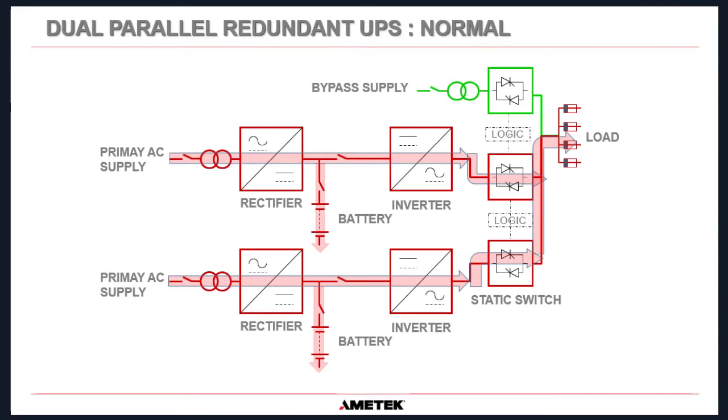Okay. So the other important thing about a redundant UPS situation is if your load is designed for, let's say, 20 kVA, you think you're going to have 20 kVA of load and future-proofed, obviously, then what you have to do is you have to have two fully rated UPSs. This one has to be 20 kVA and the bottom one has to be 20 kVA. Okay, so it is more expensive because you have to buy two fully rated systems, but it does give you the redundancy that you need. So we'll move on to the next slide.